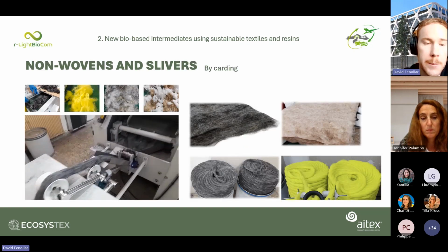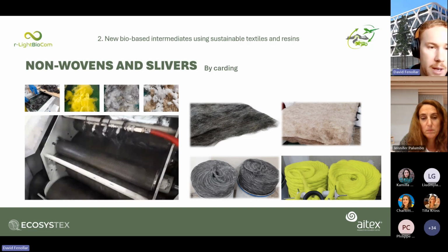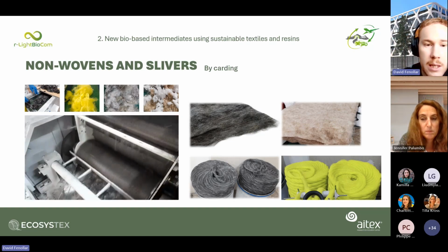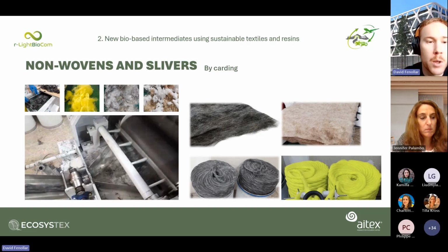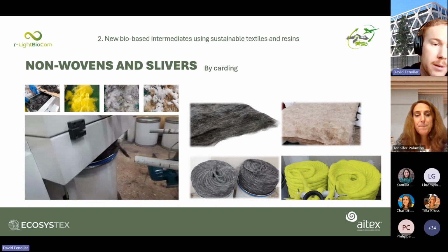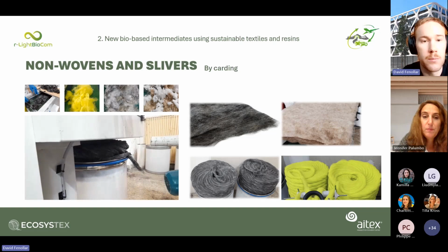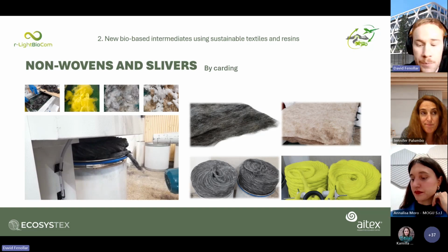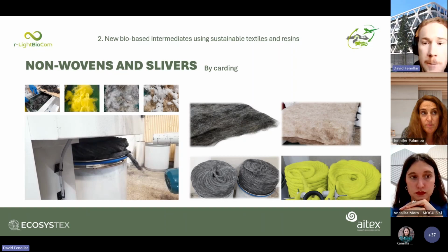This is the processing of recycled carbon fibers in our carding machine, blended with polyamide. The objective of the project is to obtain the maximum recycled carbon fiber proportions, and our objective is to reach 60% of recycled carbon fiber. Also, with aramide, we are ranging about 90% of aramide and 10% of polyamide for the thermoforming processing.